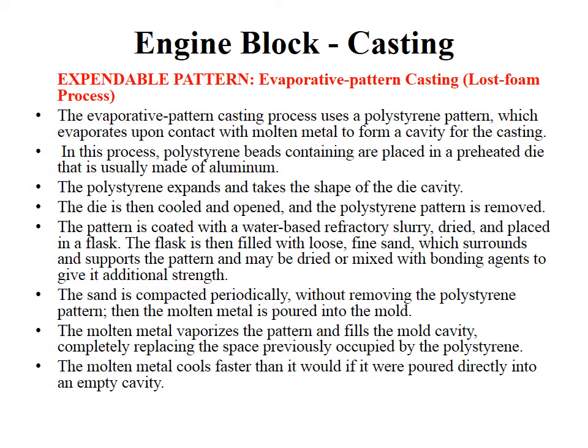So as you remember, in case of sand casting, you keep a pattern and then you pour sand into that, and then you make sure that the sand is compacted. So similarly, that pattern is made up of polystyrene here. And when you pour the molten metal, this polystyrene pattern will evaporate, and then the whole cavity will be formed, which will be filled by the molten metal, and this molten metal cools faster than if it were poured directly into an empty cavity.